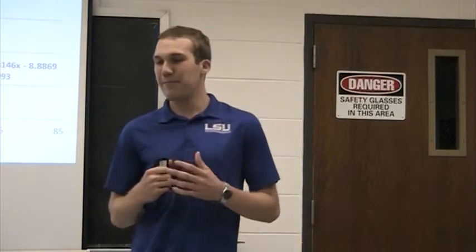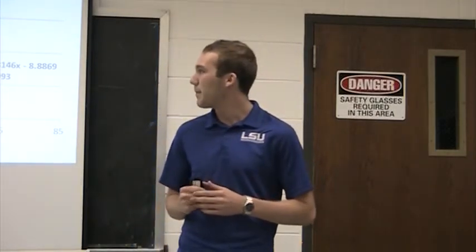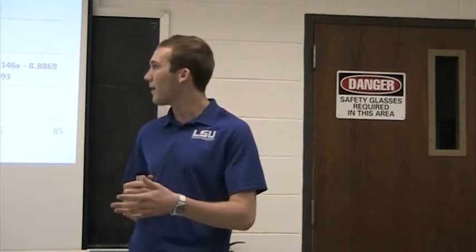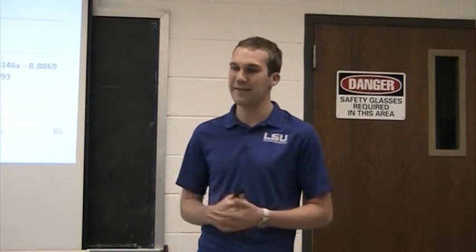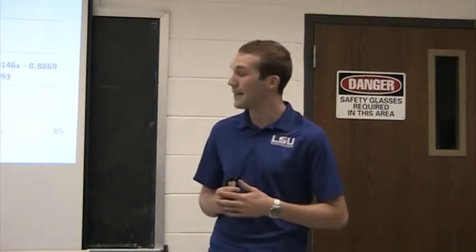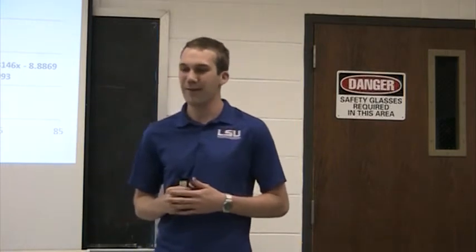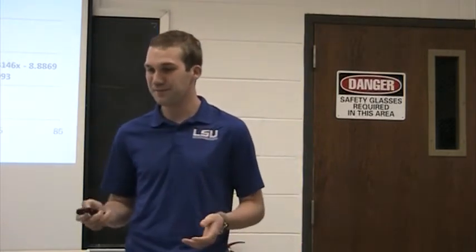We were asked in the lab manual to calculate or predict some calibration curves. This first one is the fuel flow in gallons per hour versus the RPM of the engine. These data points were given to us in the manual, and I used a quadratic fit, and the correlation coefficient is about 99.3%, which is pretty good.